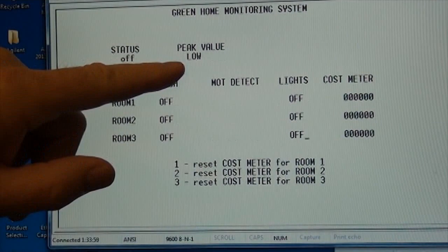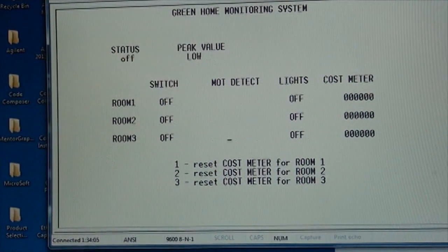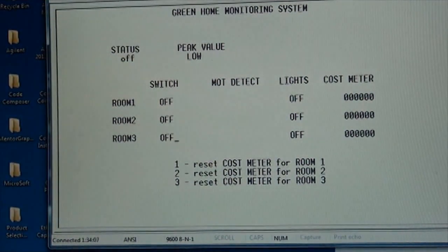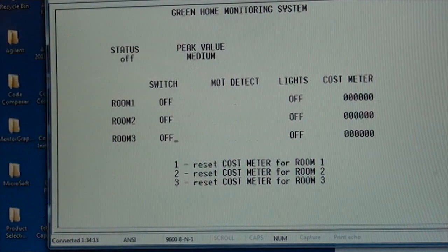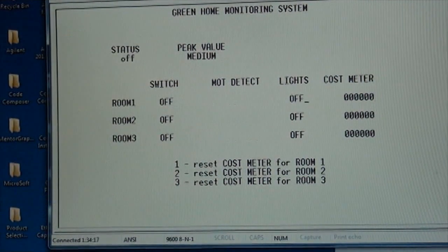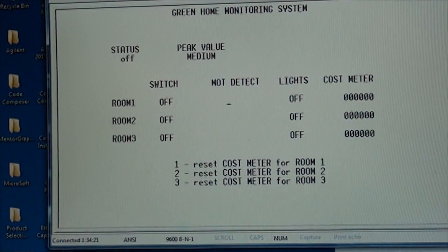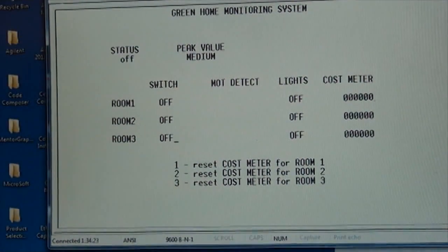Now if you've turned the speed up above 10 millihertz, then you might miss some of the readings going from low to medium. You might miss the medium and just get the high in here. So there we go, there's medium and finally high. So make sure that you've set your function generator to generate 10 millihertz, because you may miss the medium here.